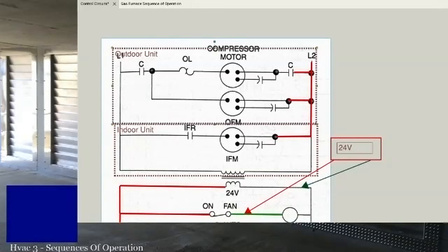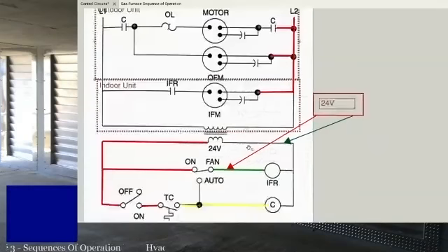You'll see some three-phase motors where it cuts off two phases but leaves one powered all the time. And you'll see three-phase systems where it cuts off all three legs of power. Every manufacturer has a slightly different way of laying it out with different units. Everything works, but it's okay to have one single power feed basically hot at all times and only cut the other leg, because the motor won't run if only one leg's out. Does that make sense?